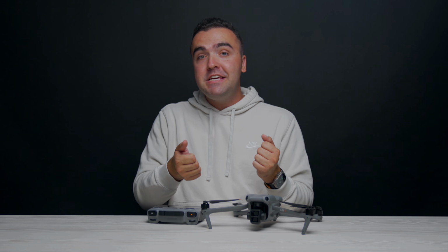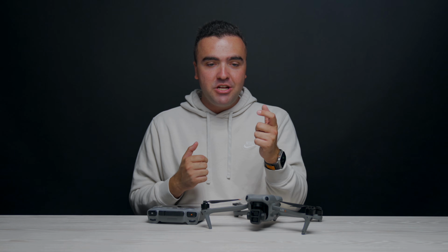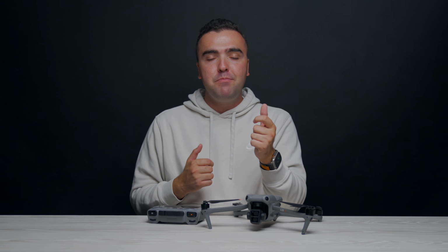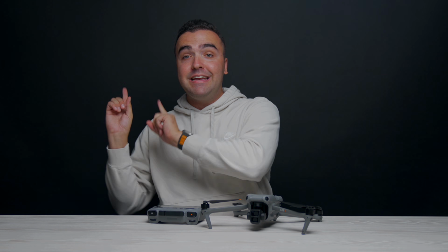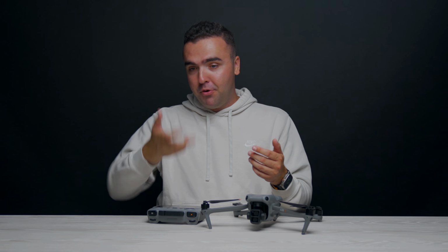So for example, you could make complex shots easier. Let's say you were chasing after a boat. You could take the fatigue off of having to push your right stick forward, hit cruise control, allow that motion to be done entirely by cruise control, and then just adjust your camera, rotate the drone a little bit, and move up and down. So it could make complex shots much easier. But in my opinion, the way that cruise control is best used is just from getting from point A to point B. Like if I was on one side of a construction site and needed to fly to the other, I would start ripping, sport mode, full speed, pull on cruise control, and then just let the drone do its thing and get to where I need to go.